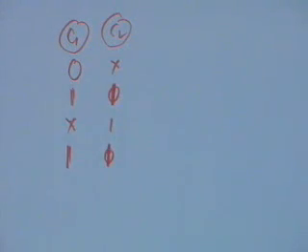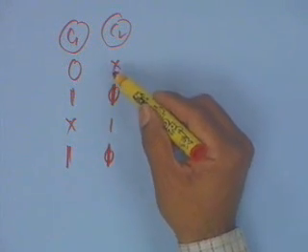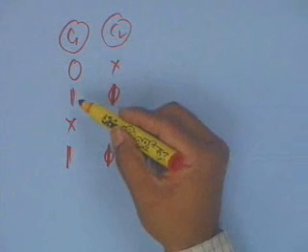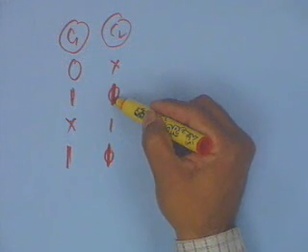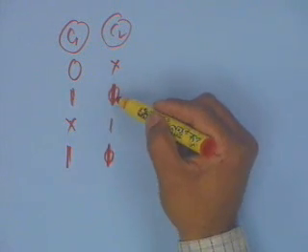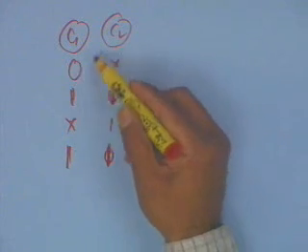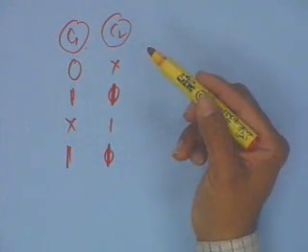this will not be detected in the first stage because we have not still considered the value. So it may happen that there is a signal which is active here, and there is another control signal which is also active here. So they are not disjoint because both of them are active, but their active values are the same. So it may be possible that we can actually merge these columns and still reduce the width of it.